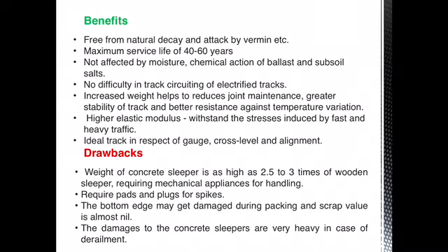But wood and metal sleepers both have very good scrap value, whereas concrete doesn't have any; the depreciation cost is zero. The damage to the concrete sleepers is very heavy in case of derailment, and it may require frequent change of the concrete sleepers.